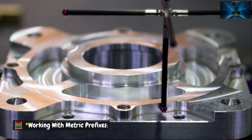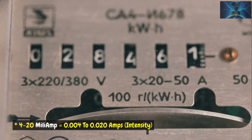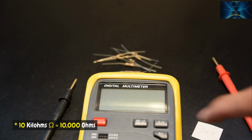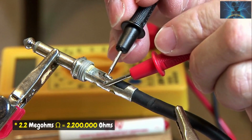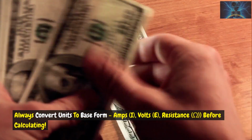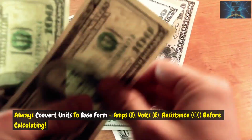Working with metric prefixes. Instrumentation deals with a wide range of values. 4 to 20 milliamps equals 0.004 to 0.020 amps. 10 kilo-ohms equals 10,000 ohms. 2.2 megohms equals 2,200,000 ohms. Always convert units to base form, amps, volts, and ohms, before calculating.